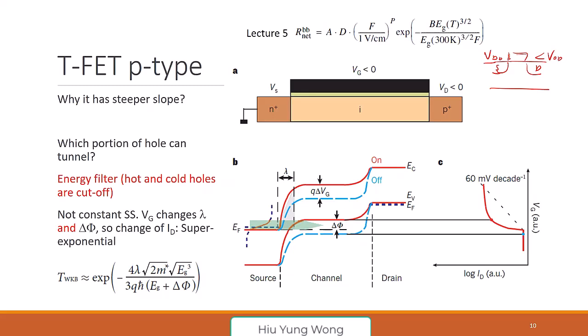Okay, yes, you can say ground, right? How about gate? VG, whatever the turn on voltage we require. I mean, what is the range? How do you turn on the PMOS? For example, if VDD is 5, what voltage do you need to put to turn on the PMOS? One threshold below VDD. For example, VDD minus VT.